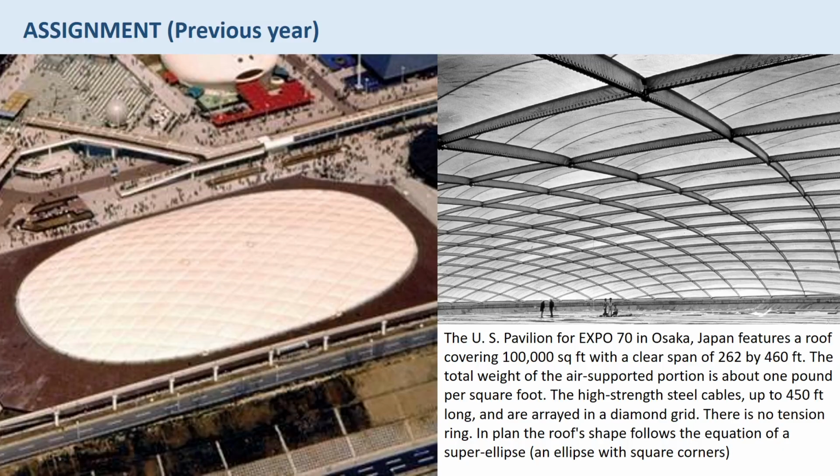Question number 11. Which of the following is not a member of a truss? King post, rafter, purlin, hoop iron. King post is a central vertical post used in architectural or bridge designs working in tension to support a beam from the truss apex above. Rafter is a long board that supports the peak of a roof. Rafters are a type of beam, a heavy supportive board that holds up whatever is above it in a building.